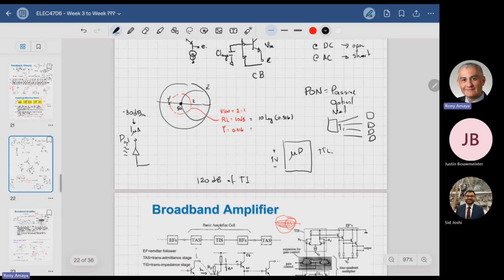Okay. All right. So then you're asking me, what do we do with this? Well, the first thing we have to do is we have to sense it. And the first block is really critical. So we actually use a transimpedance amplifier to give us probably about 40 dBs of transimpedance, dB ohms. Okay, so that means that you have 1 microamp, 40 dBs is equal to what? 100, right? So I have 100 microvolts on the other side.